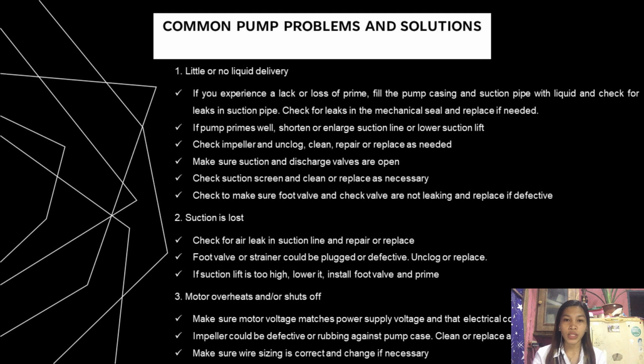The solution is check for air leak in suction line and repair or replace. Foot valve or strainer could be plugged or defective, unclog or replace. And if suction lift is too high, lower it, install foot valve and prime.